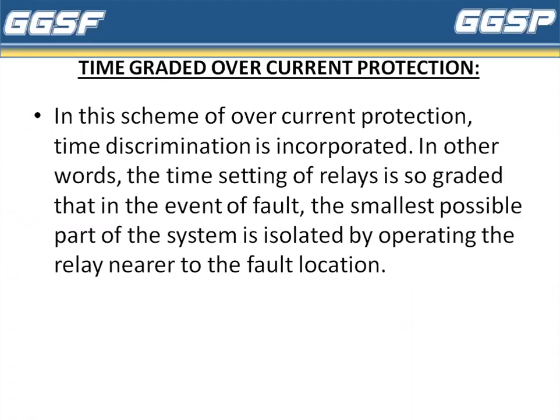Time graded over current protection. In the scheme of overcurrent protection, time discrimination is incorporated. In other words, the time setting of relays is so graded that, in the event of fault, the smallest possible part of the system is isolated by operating the relay nearer to the fault location.